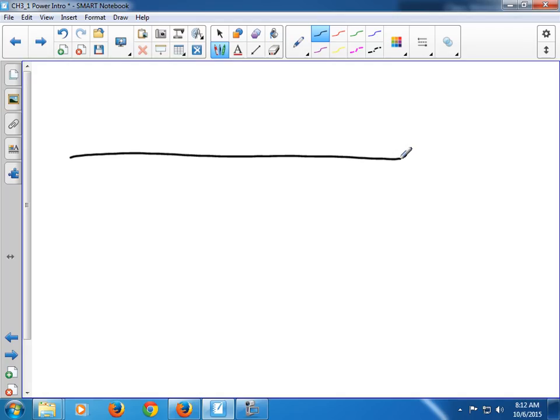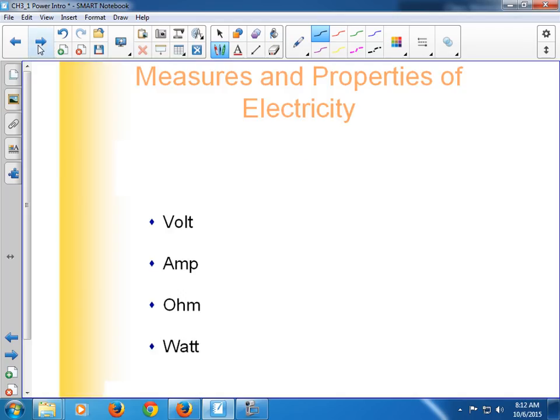All the power in these aircraft systems was alternating current until it got down to right there at the instrument panel, and it was changed into direct current for whatever that instrument was. In fact, there are some instruments in the aircraft that just ran on 3-phase AC because they used so much power. Direct current power, DC, just has a voltage. And we're going to talk about what voltage is, but it's flat. It does not cycle at all, and that's why it's good for electrical components.